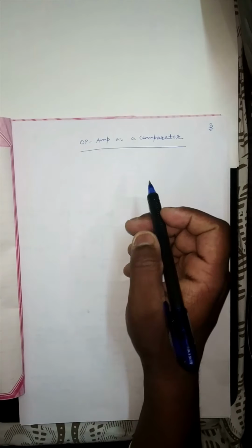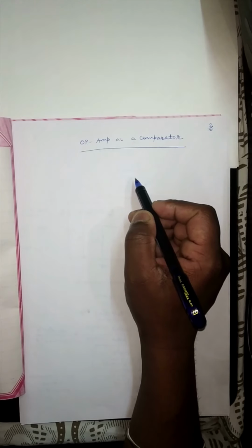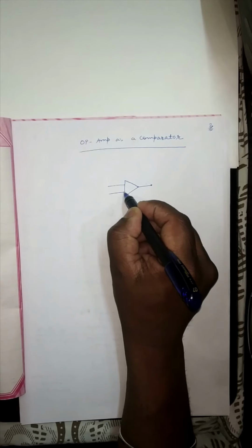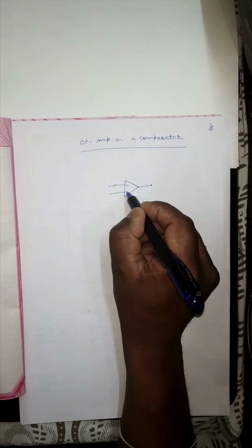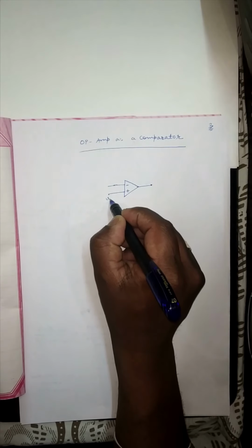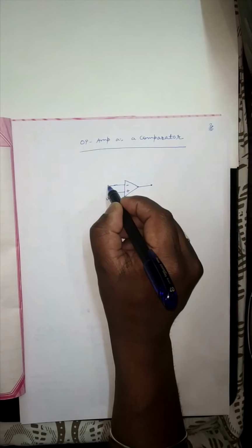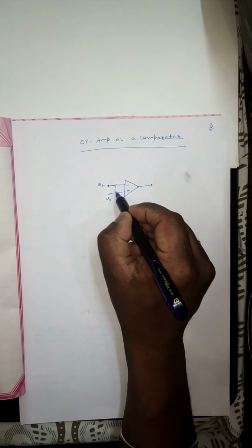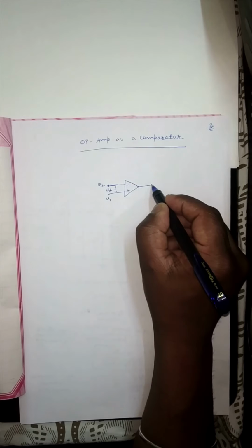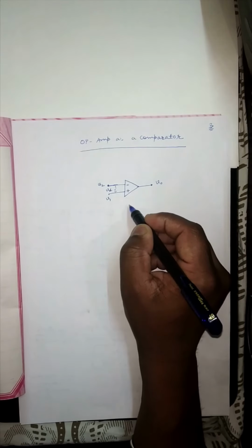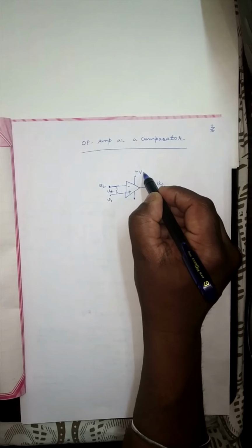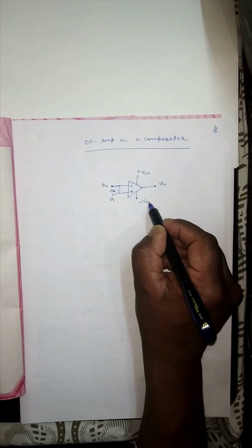Basic function of this comparator is to compare the two values of the input voltage applied at the inverting and the non-inverting input. Now we are having operational amplifier with its two inputs, that is inverting terminal and non-inverting terminal. Let V1 is the value of voltage which is applied at the non-inverting terminal and V2 is the voltage which is applied at the inverting terminal. Let Vd is the potential difference between these two terminals and Vo is your output voltage. So we have two more terminals. These are called as the reference terminals. One is plus VCC and second is minus VCC.